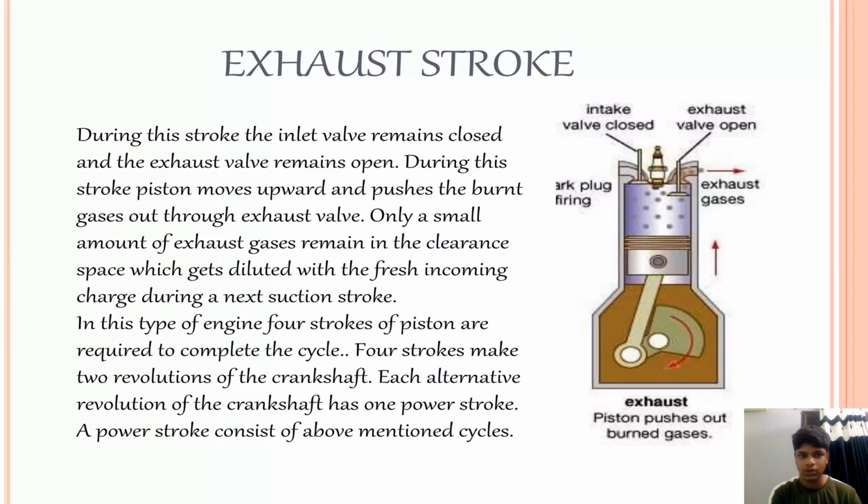Next, exhaust stroke. During this stroke, the inlet valves remain closed and the exhaust valves remain open. The piston moves upward and pushes the burnt gases out through the exhaust valves. Only a small amount of exhaust gas remains in the clearance space, which gets diluted with the fresh incoming charge during the next suction stroke.